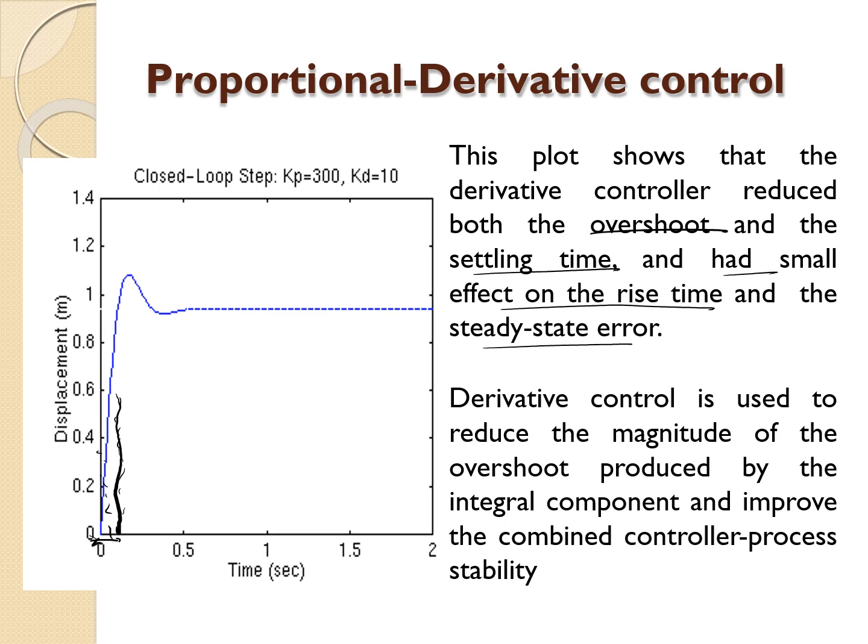So as compared to the response for the PI and P just now, PD will reduce the rise time, and also the settling time reaches fastest as compared to the PI and also P response.